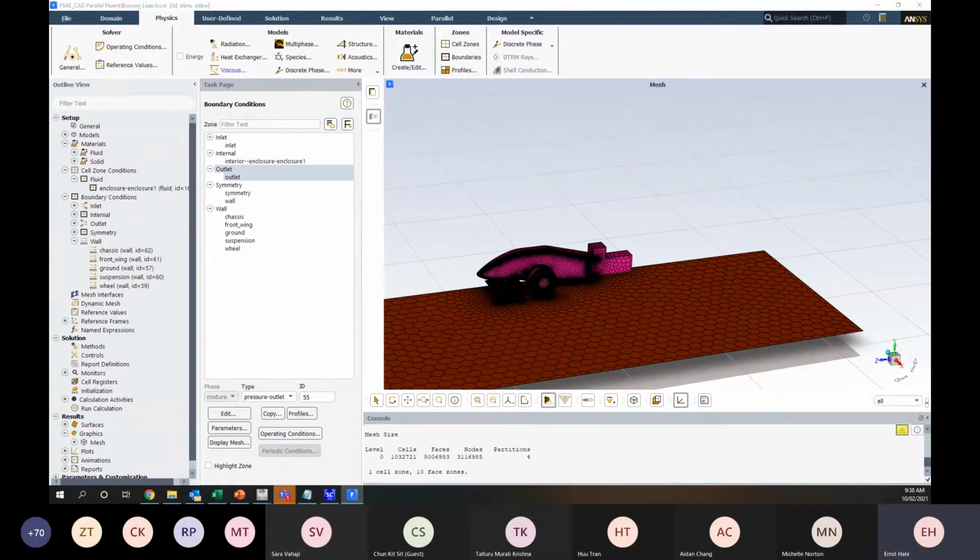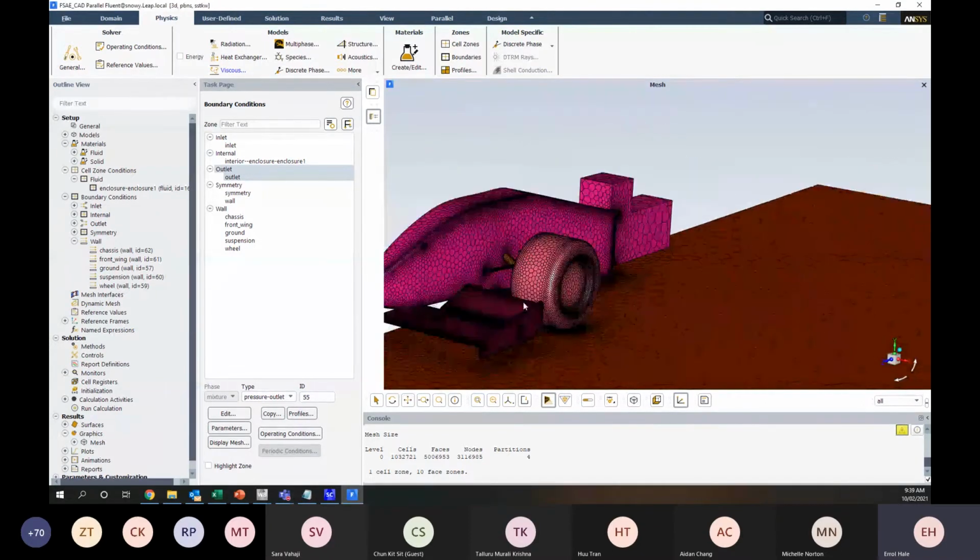Okay, this is another question. In this type of simulation, are we assuming the entire model to be rigid? Yes, we are. Wheels will be rotating, so there'll be a velocity on the wheel surfaces, and the ground will be moving. But I'll show you the wheel compliance and the VD, so vehicle dynamics, so your shock absorbers, and then they'll actually be dropping as well, depending on how high the fidelity of the simulation. In this case, generally it's a pretty good approximation to have everything solid.